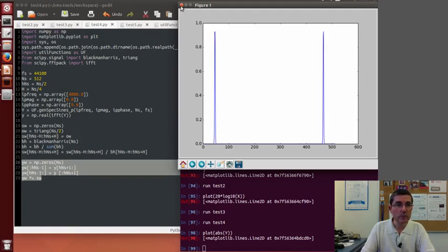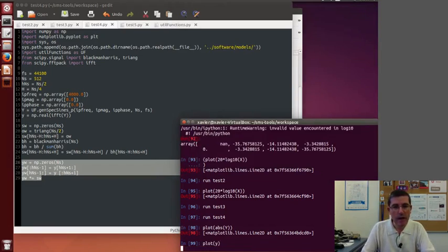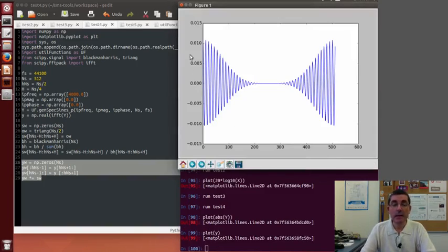Okay. Then what we do is we compute the inverse DFT, so we can plot the inverse DFT of that. So let's plot y, okay, and this is the Blackman-Harris windowed sinusoid in the time domain, in which we see it centered around 0. So we see the second half of the window at the beginning and the first half at the end. There is no zero phase here. Well, there is no zero padding because we actually had the same window size and FFT size, which was 512.